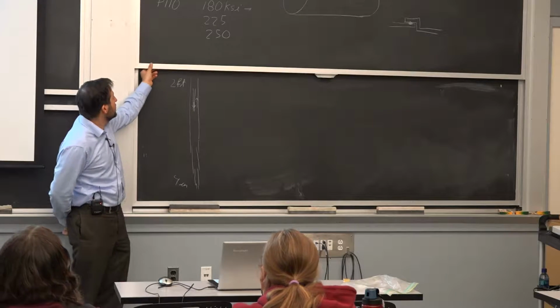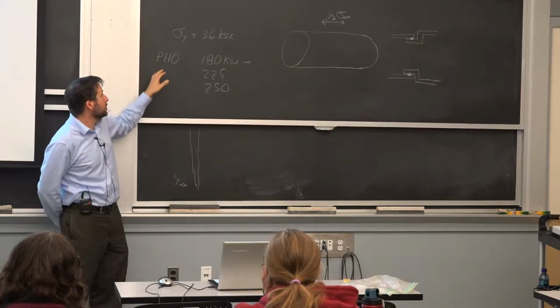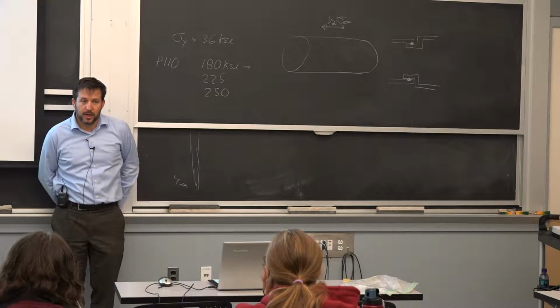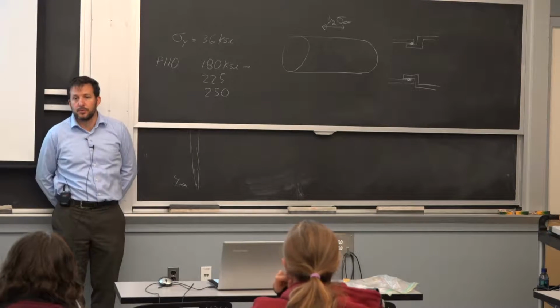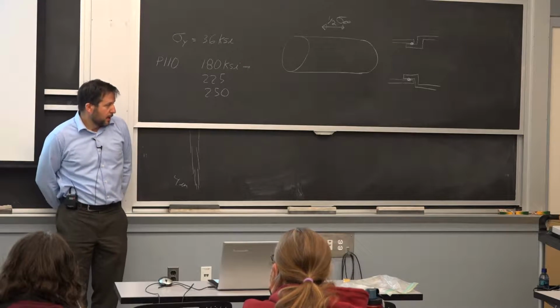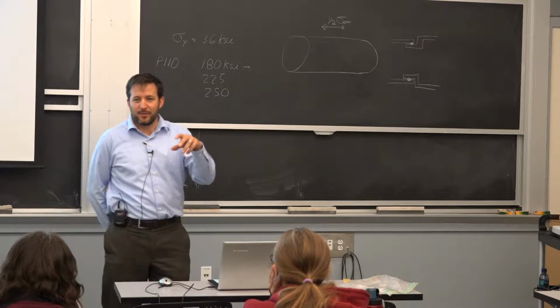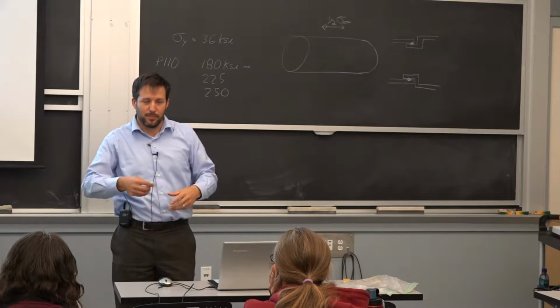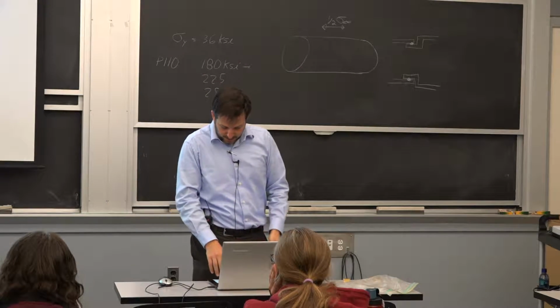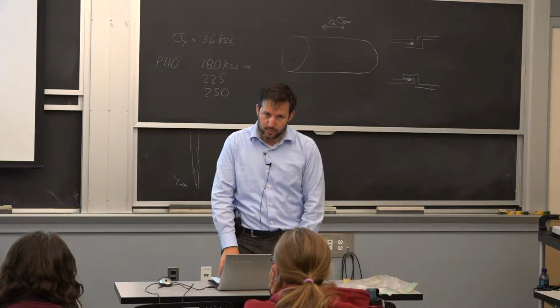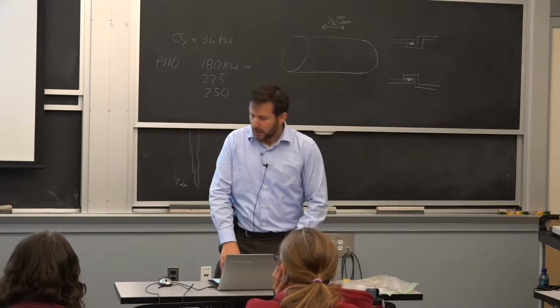So this limit here is actually very, very close to the maximum where you'll start having the problem of stress cracking in service, and you of course want to avoid that, because when you're 5 miles down and it breaks, now they have to bring the fishing tool and pick it up, and every day on the rig is very expensive, so they try to avoid that as much as possible.